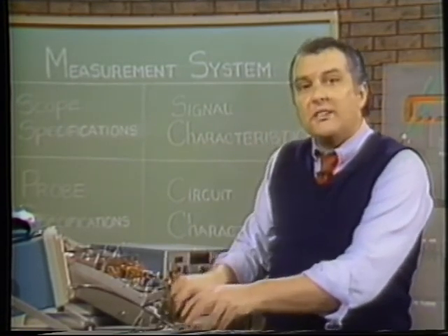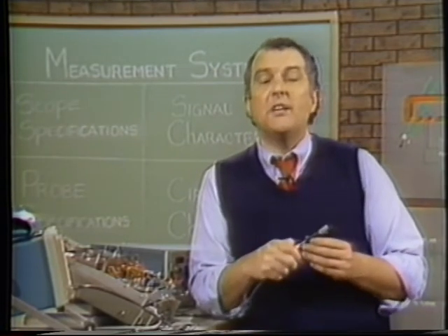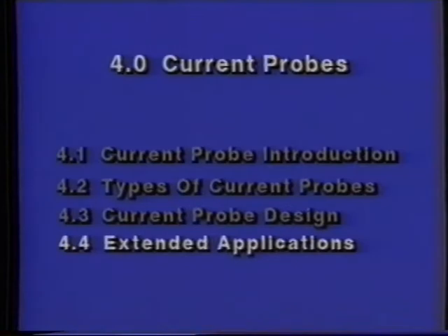A typical AC and DC responding probe runs DC to 50 megahertz with a rise time of 7 nanoseconds, aberrations of plus 5%, minus 5%, and 7% peak to peak. It's capable of measuring to 20 amps DC or DC plus peak AC and a single shot pulse peak to 50 amps.